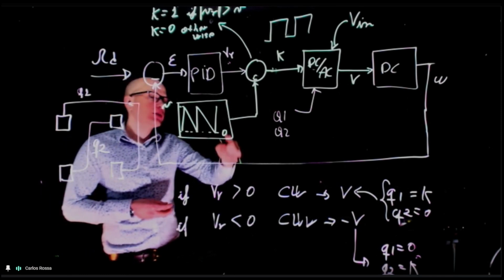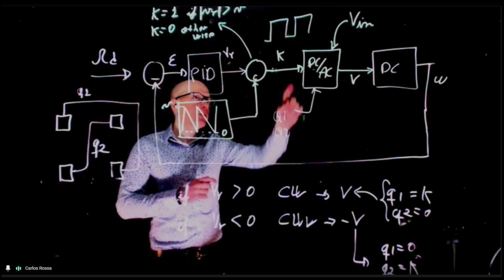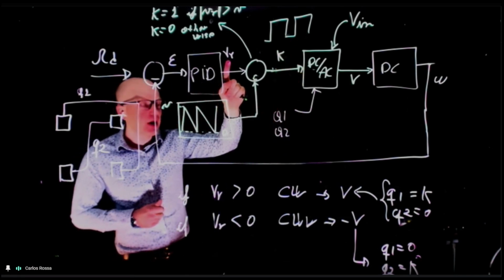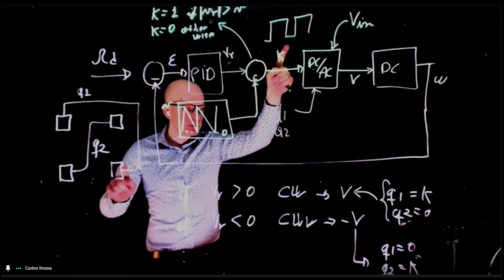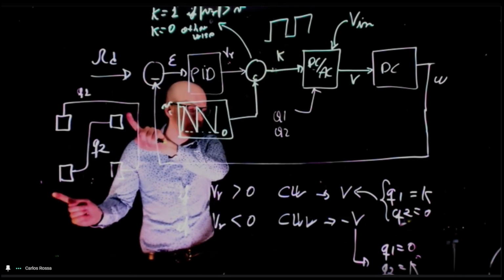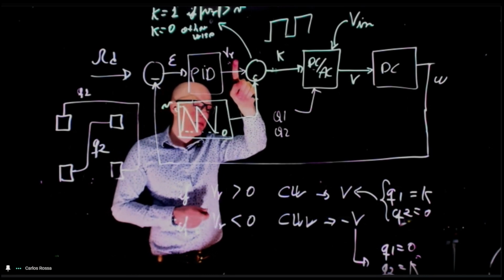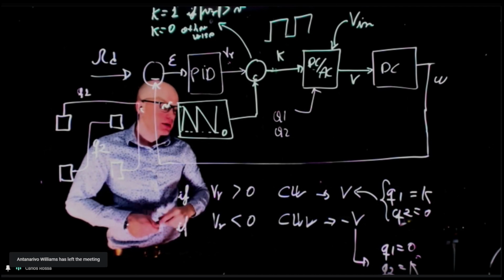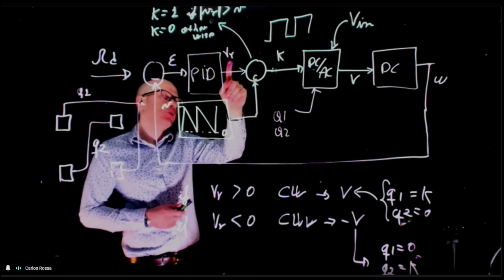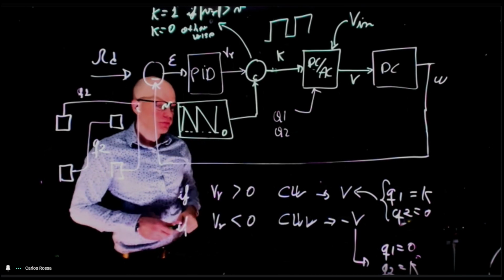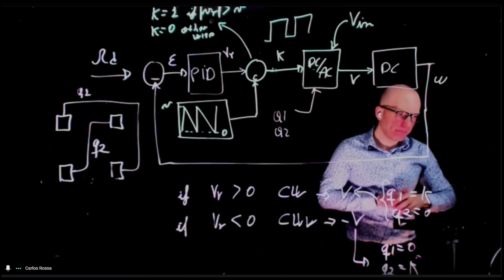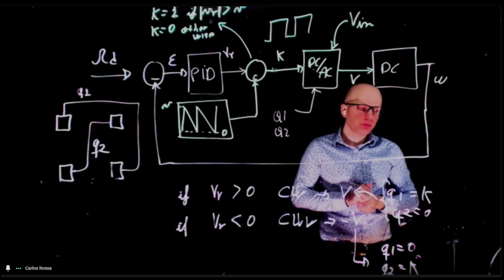And then once that is done, we have determined the duty cycle. The question is, was this positive or was this negative? If it is positive, give it to this branch. If it's negative, give it to the other branch. So we throw away the sign first, but then, once we determine which branch takes that duty cycle, we actually have to look back at the sign here. Does that make sense? So you take the magnitude, and that's where you find how much you want for your K.